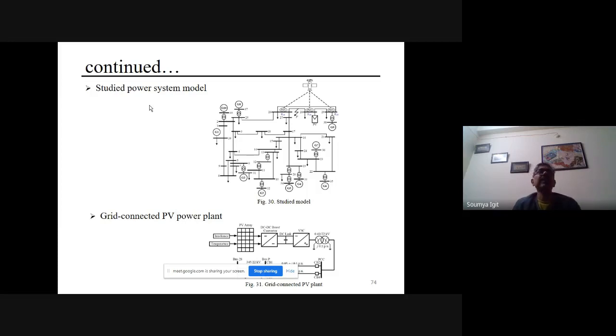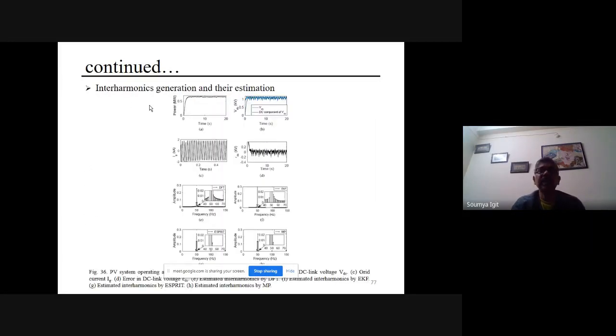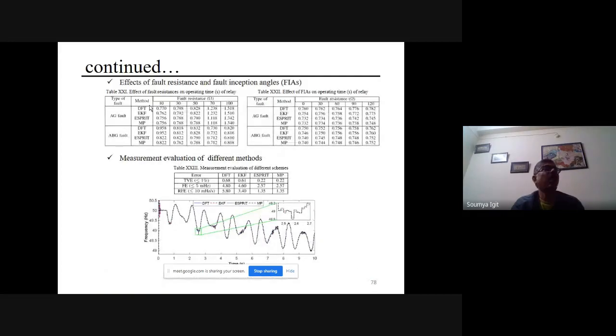So there you go for different parametric and non-parametric based approaches in the signals, and subspace based approaches with different frequency selective components that you separate in order to get the pseudo phasors as per the PMU standard. That means you are getting the signal from the remote end, and you are getting the fundamental phasor extraction for the decisive action of the distance relay, as far as the zone 3 backup is considered.